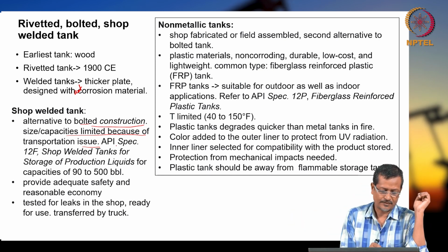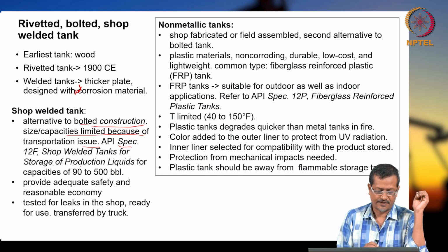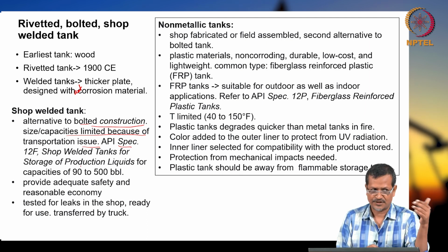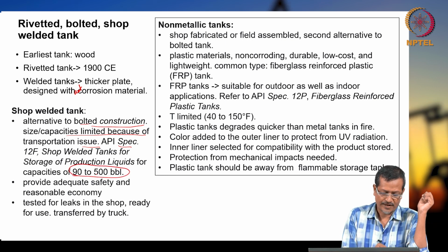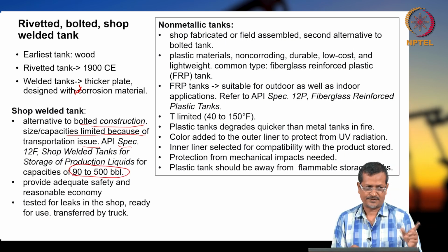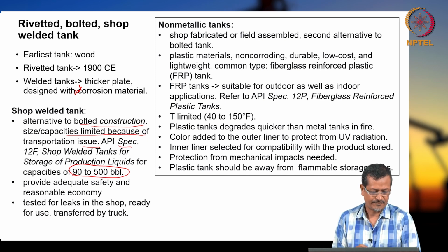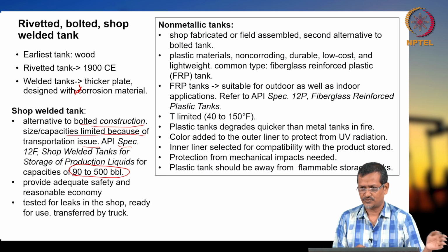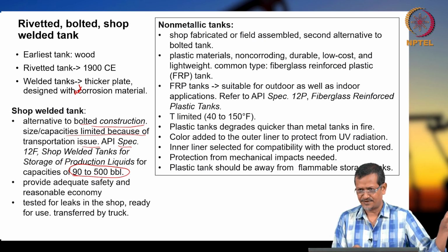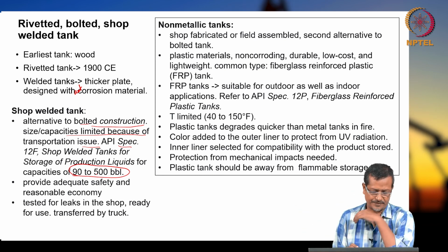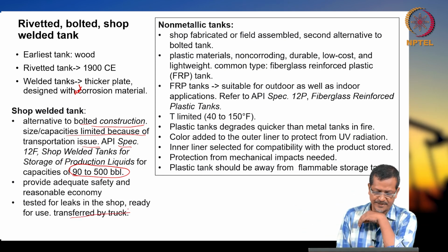API spec 12F describes how to design it, the different design calculations and parameters, and you see the capacity is 9 to 500 barrels, very small actually. Okay, it provides adequate safety and reasonable economy. Leak testing can also be done in the shop, so it is better for smaller applications. In the shop you test everything and then just put it in the field. Okay, ready for use, transported by truck.